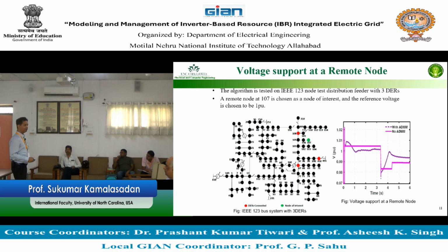I think I have a graph with photovoltaic connected. This regulator gets messed up because the regulator sees the load side, and when there is a voltage drop, the regulator taps up. So the voltage drop happens when the load is there. Let's assume you have a photovoltaic there. The load is changing, but the perceived load changes because PV is pushing to that load, which means the regulator will see a light load.